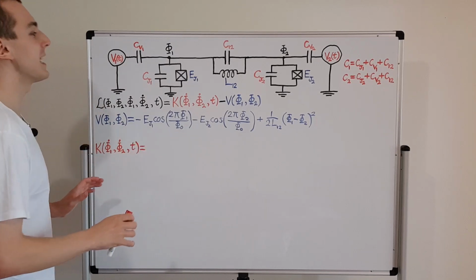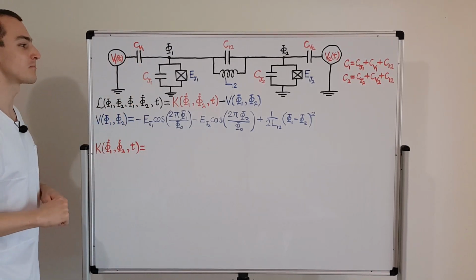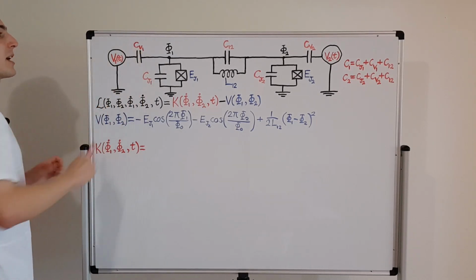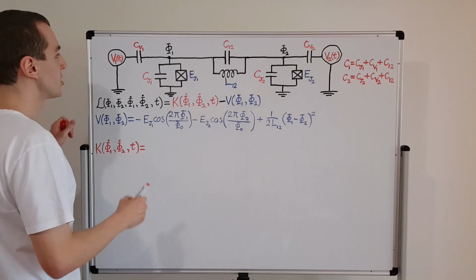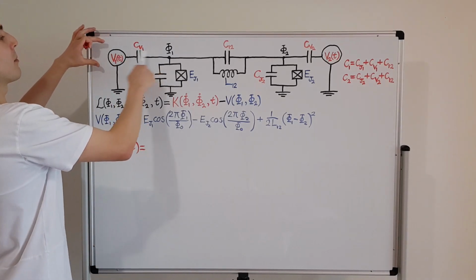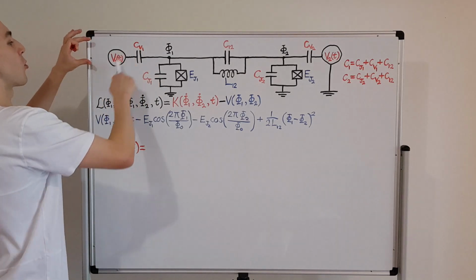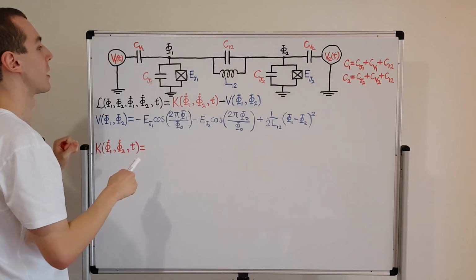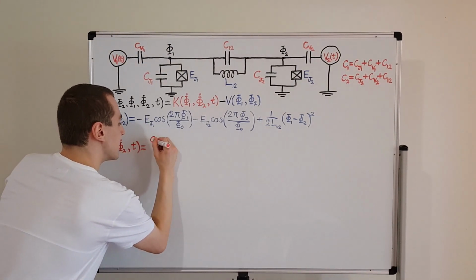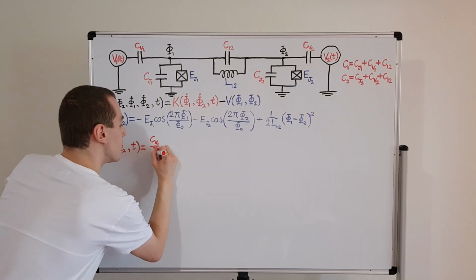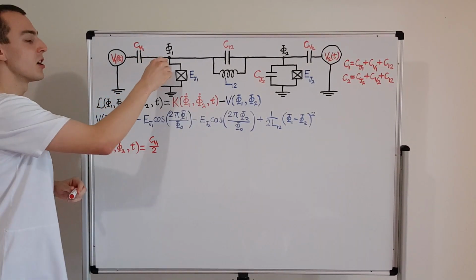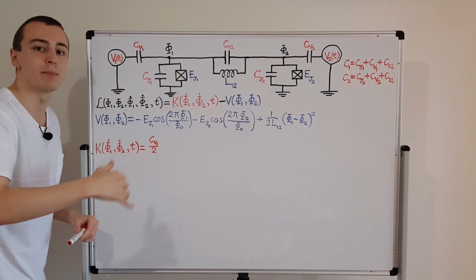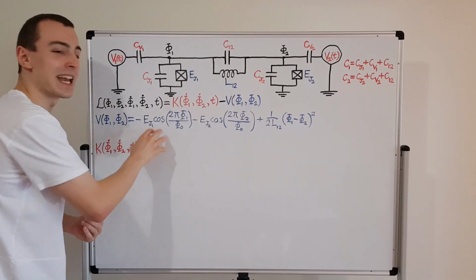There's a lot more going on in the kinetic energy because we also have those driving terms. So what we have to do is consider all of the capacitors. Let's start off with this capacitor over here, CV1. CV1 is this coupling capacitor which couples to the external driving voltage, which is associated with the first oscillator, oscillator 1. So that's going to have the form CV1 on 2, and then we want to take the difference of the phi dots. Now, instead of phi, we're going to have phi dots, because the capacitors depend on the velocity. They are analogous to the kinetic energy.